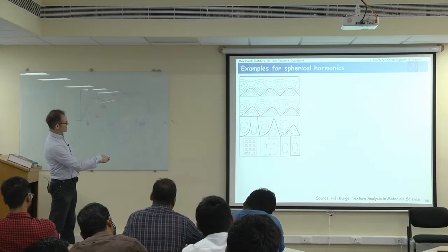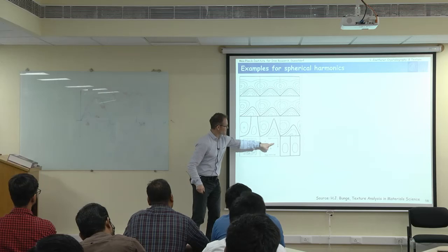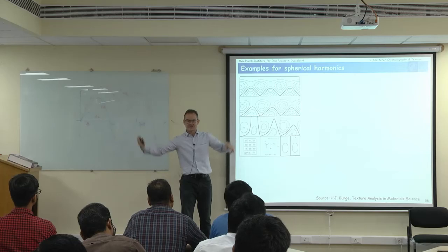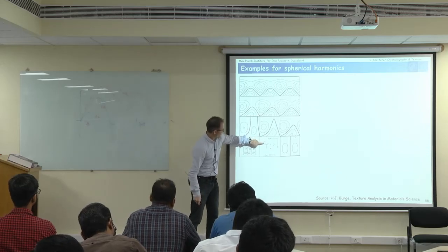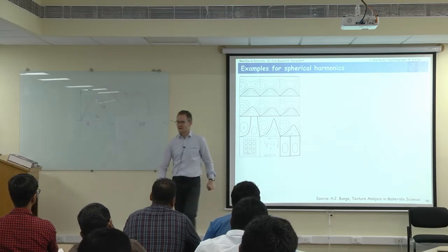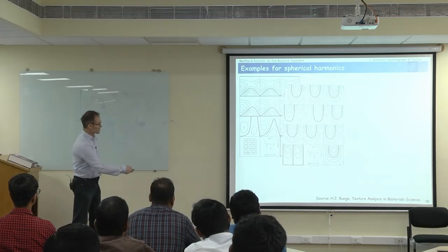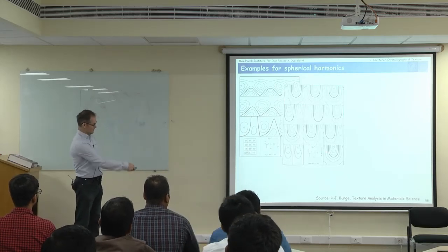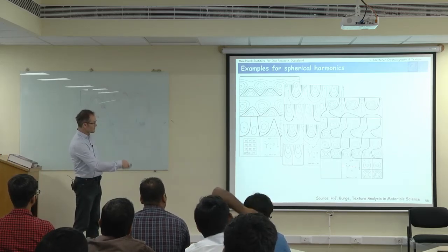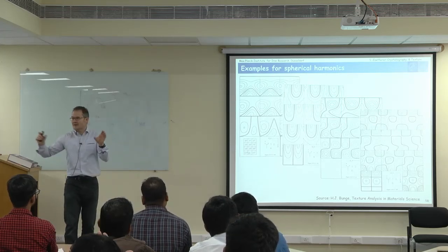So this is, for example, the spherical harmonics for the function T124. This means how far I expanded, how many sines and cosines I add, for cubic crystal symmetry and orthorhombic sample symmetry. And this is T144, a higher development, and it's already finer. This is still finer, T126 and T146. And you see these things become finer and finer.